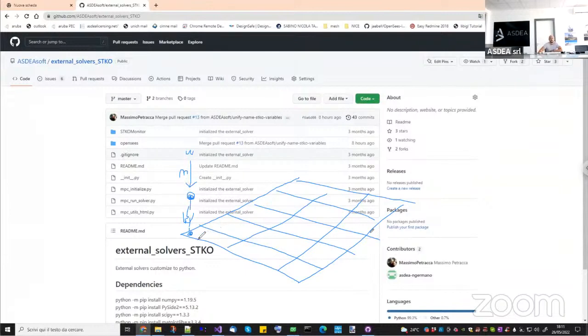And the idea would be to let the user define a trajectory for the passage of the train. And then, at a certain time step, this node would be, for example, here. What we want to do is to compute the projection of this node, and then to understand what is the element this node falls into. For example, in this case, it will be this element. And then we want to apply a particular constraint, such that this node will move as a weighted average of the displacement of the other nodes.